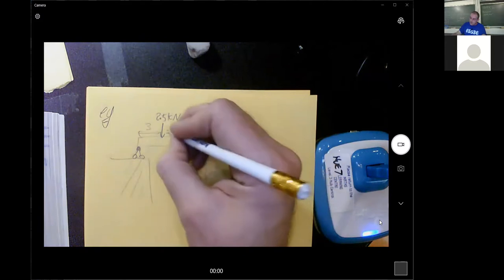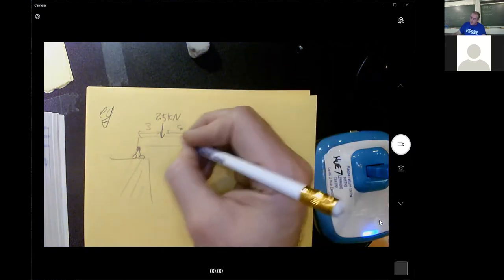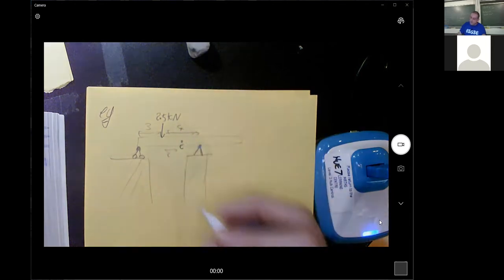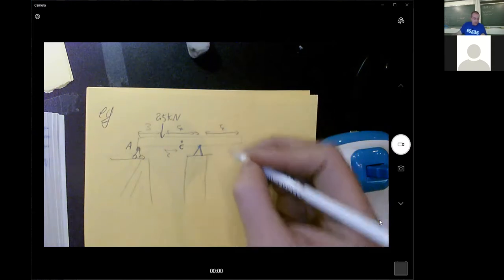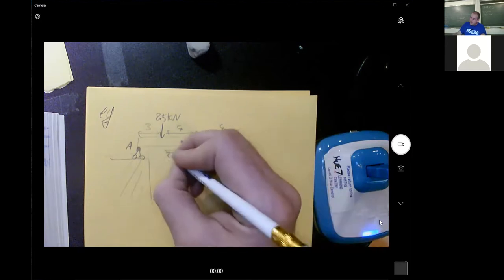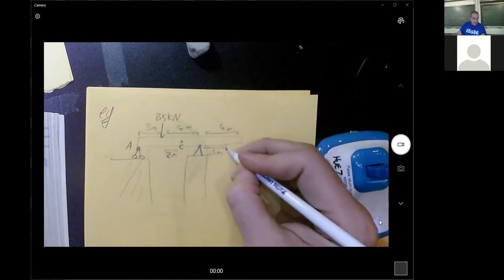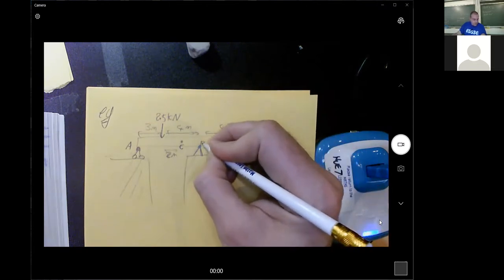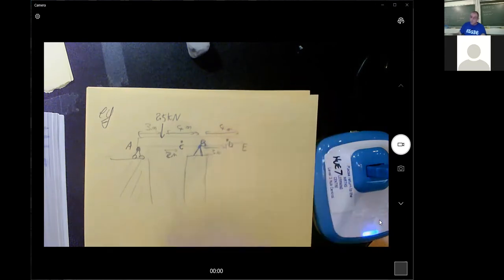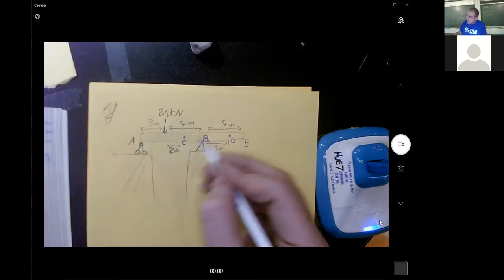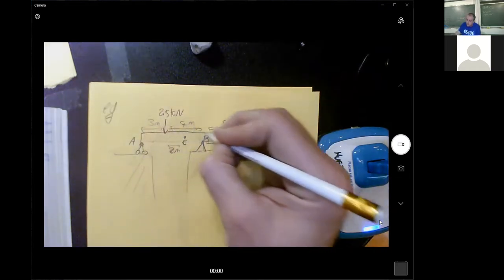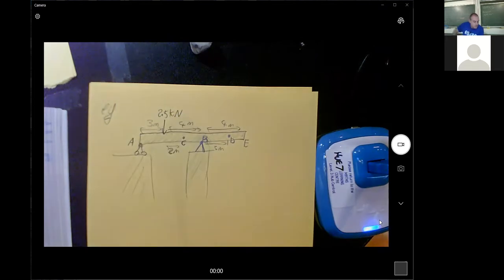And then this is 4 meters, and at the position of 2 meters, there is a point which they have called C, and they've called this point A. And then they've got 4 meters this way, cantilevered out the end, and at a position 3 meters along here, they've got a point which they have labelled D, and this one's called B, and this one's called E. The shear force and the moments at the points C and D they're asking for.